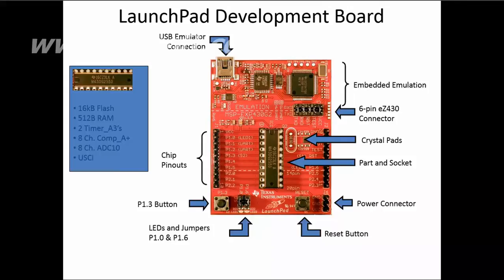TACLK, TA0 and TA1 are associated with Timer A. TACLK can be used as a clock input to the timer, while TA0 and TA1 can be either inputs or outputs. These can be used on several pins because of the importance of the timer, which we basically use for clock frequency.